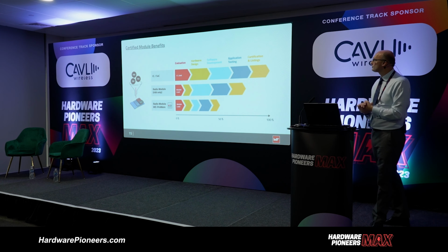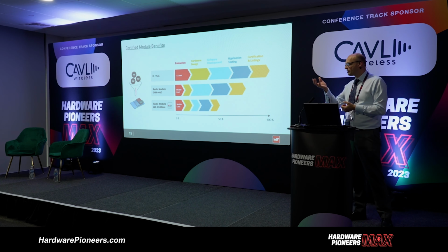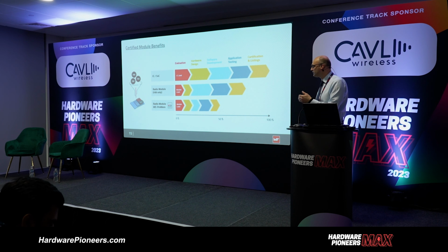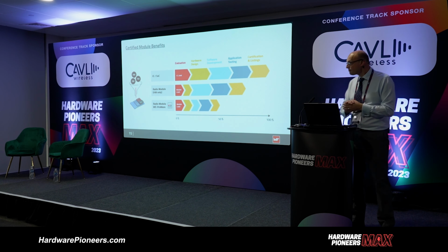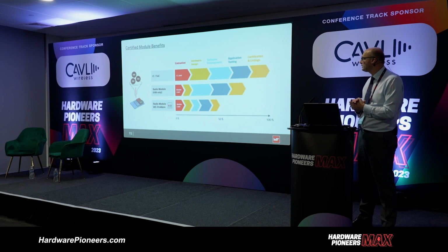Second one, we then have the RF module. So just looking purely at hardware, you can take a pre-approved module. The hardware design built around that module is more about the power supply, what the host device and its application, its performance need. More time goes into developing the software. Once again, validation, application testing, and then certification.